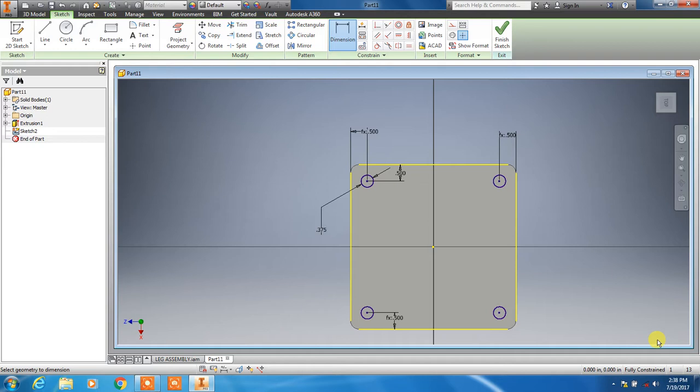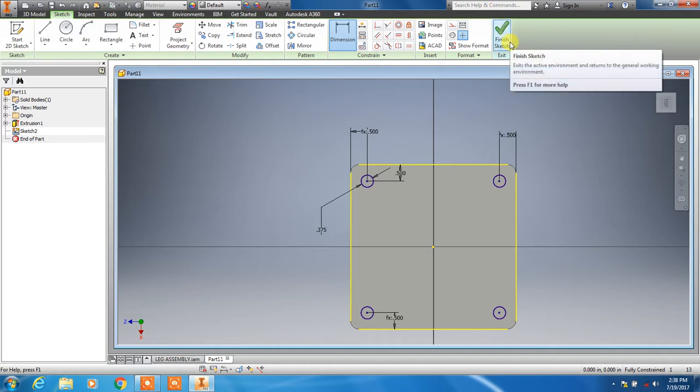Now, it would have been a little quicker had I just put a point there, but the reason that I went ahead and drew the hole was because a lot of us have CNC plasma tables. So now I've already drawn that drawing. I can take that drawing right straight to my plasma table and convert it and burn that plate out and not have to worry about a kid getting the hole points off or getting the bolt pattern wrong.